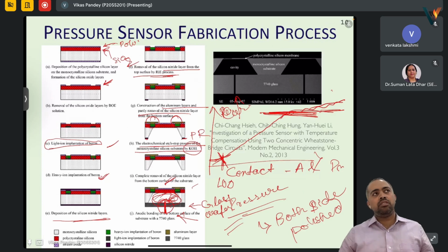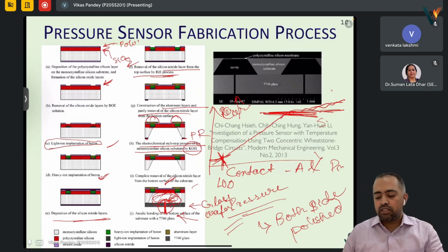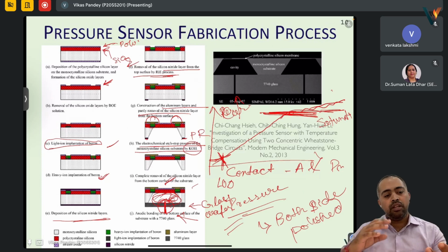Highest, you will generally see that there is saturation. We call it saturation of the sensor. After that, it might not break at that point itself. It will saturate. The changes will not be able to reflect their effect on the resistance or whatever mechanism you are using.